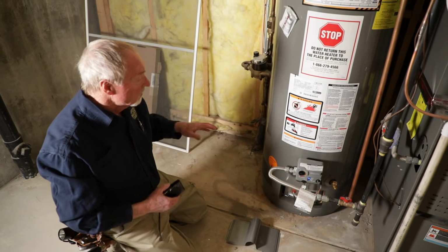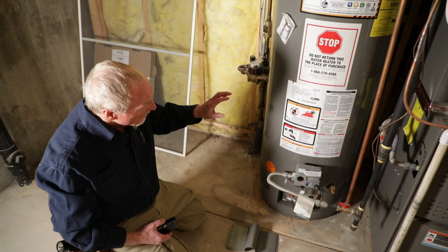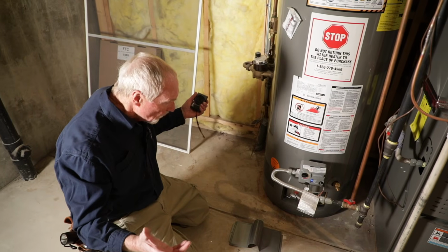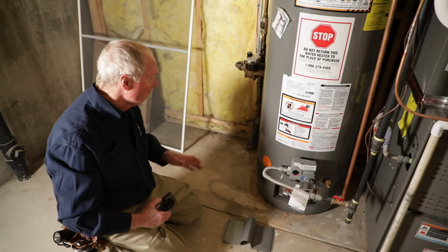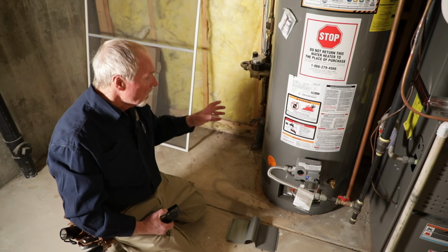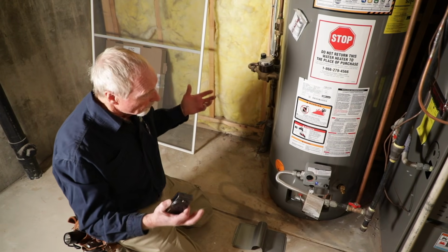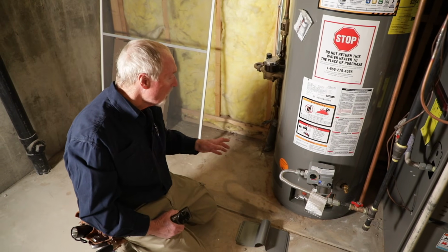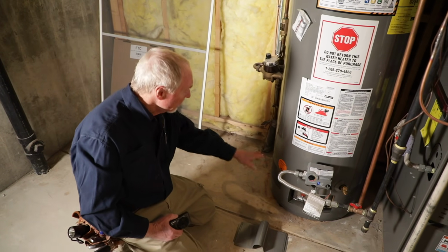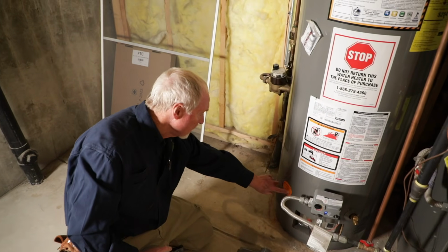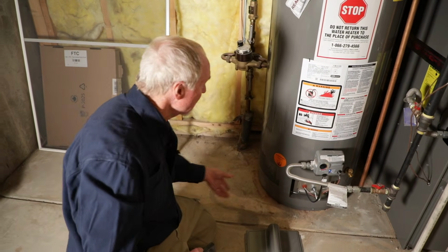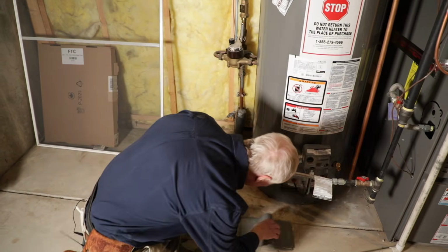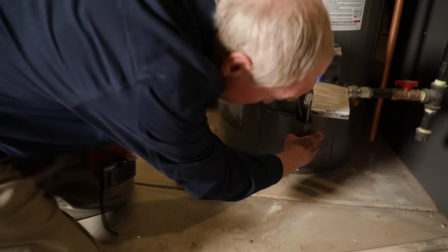It's always nice to turn on some hot water, force the unit to come on, and we can see how the burner plate is burning, and sometimes see some rust or debris that has fallen in on the burner plate, which might indicate an issue, a problem going on. Little things. We have a sticker here that says do not block this combustion air intake here. Good, it's not blocked. That's a nice thing to see. Put our cover back on here.